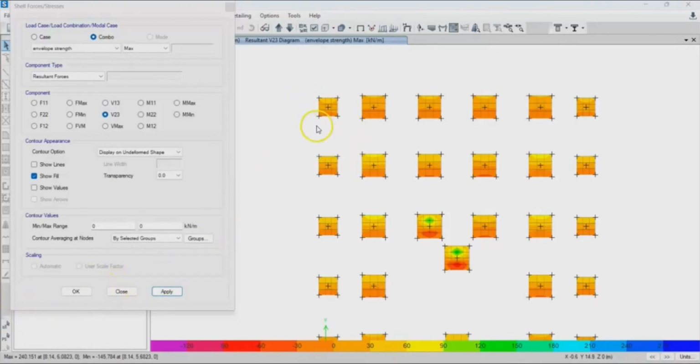Okay, so if your footing is failing the punching shear, and probably also failing the one-way shear check, then what you need to do is increase the thickness of your footing, right? Because if it is failing the punching shear, meaning the column is trying to punch through the footing, your footing is not thick enough, so you have to increase the thickness of your footing.